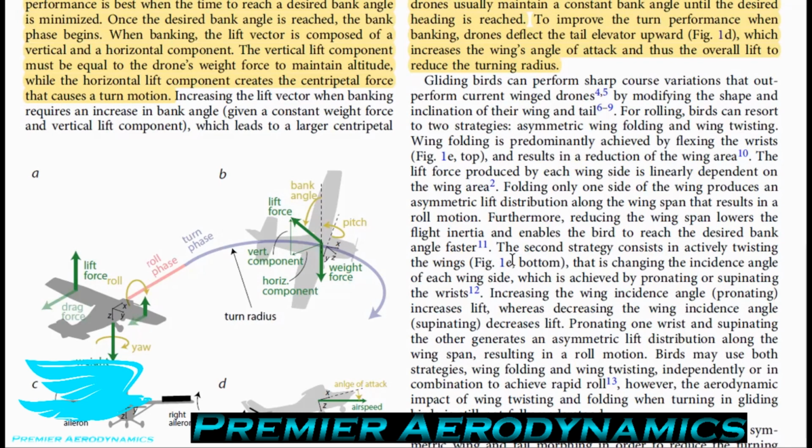So if you were to break the lift force down into the vertical and the horizontal directions, there's a component in each direction now. Again, the lift force will have some part of its force going straight up with respect to the Earth, but there's also going to be a part horizontal with respect to the Earth. The airplane, however, doesn't understand any of this. It's just a lift force which is always perpendicular to the wing surface.